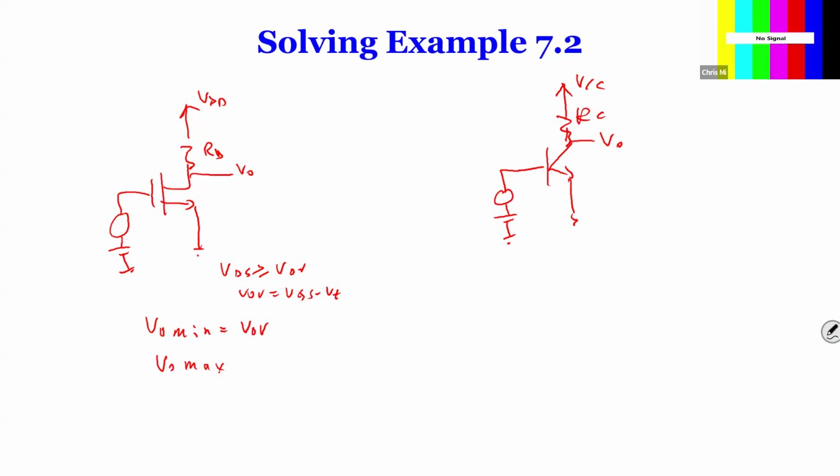But at some point, what happens? You're going to reach the absolute maximum. So your absolute maximum often is just VDD. I mean, ideally it's VDD minus ID max times RD. So it depends on how you find ID min, not ID max.